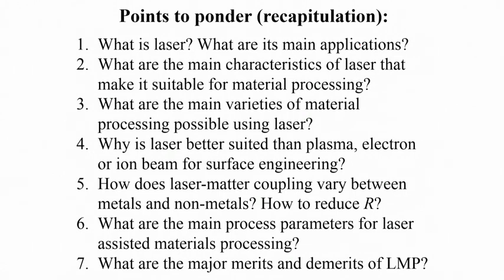Everything is good about laser, but the capital cost is very, very high, and you also need a fair amount of skill for making correct use of laser for various materials processing. But on the other hand, the biggest advantage is that it's an extremely fast process. Another major demerit is that the beam size is typically in the order of millimeters or less than a millimeter, whereas a bulk solid that you're talking about in terms of volume or surface area is way too high, much higher than the size of the beam.